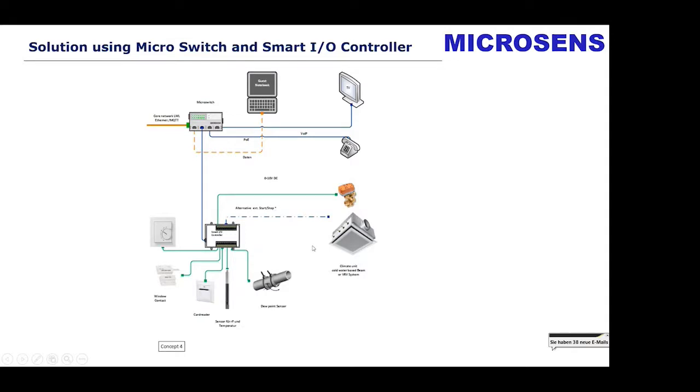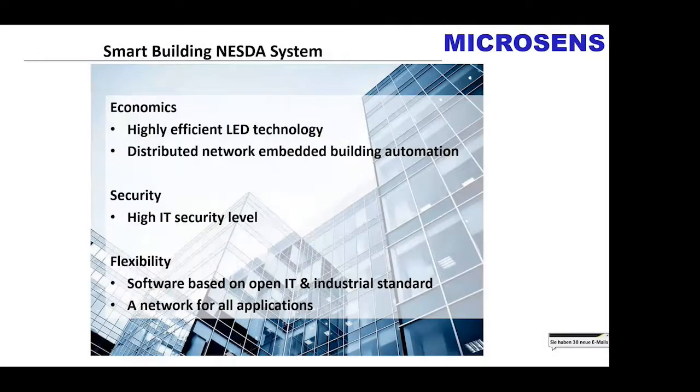The need of power for field components is quite low. For example, one of the biggest consumers is a valve, which takes roundabout 5 watts. All the other devices like card readers or sensors need really little power, so the 20 watts which a smart I/O controller is able to run allows us a lot of applications.